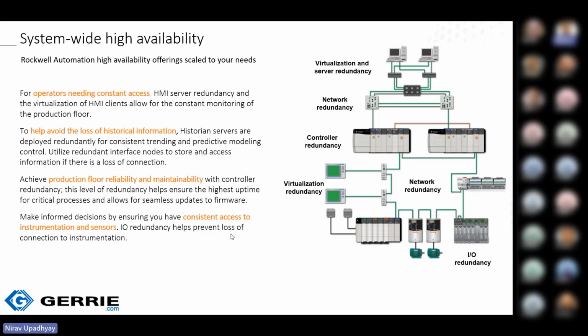downtime of 52.6 minutes per year, and with redundancy it is 99.999%, which is 5.26 minutes per year. Servers, controllers and IO are hot redundant with bumpless transfer. And the architecture supports a redundant network with ring and DLR options.